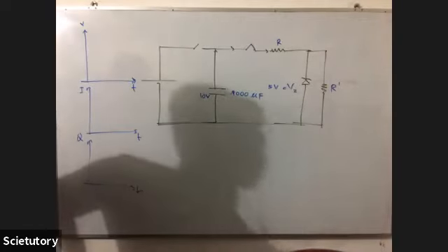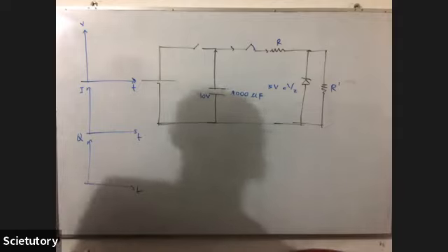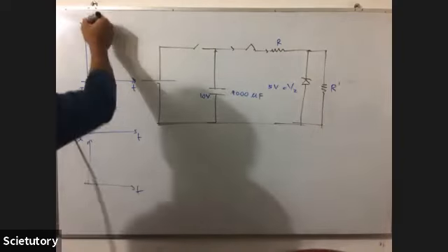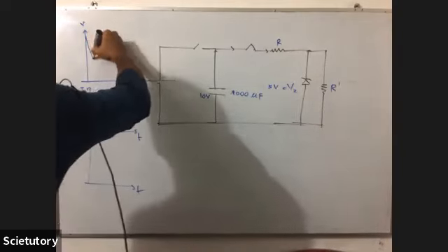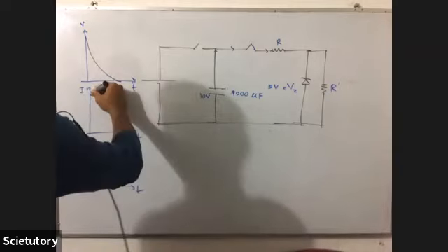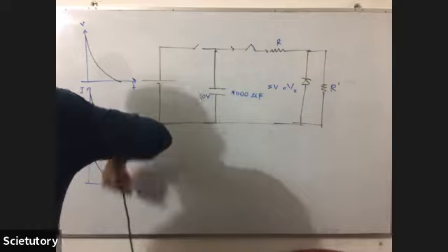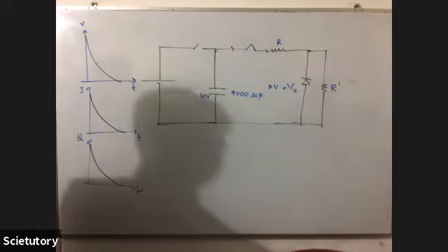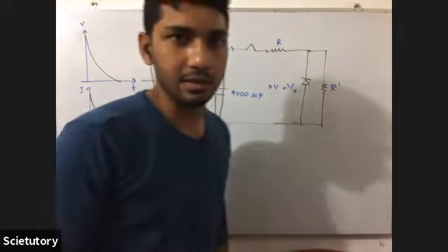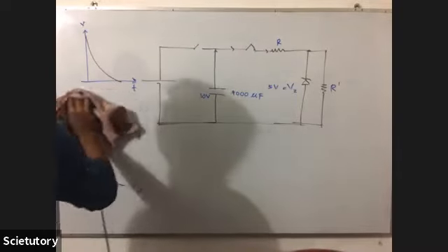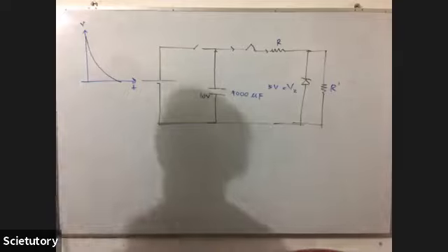When it's discharged, it rapidly supplies the charge to the rest of the circuit. So the voltage difference between the plates reduces and finally becomes zero. I is also reducing and becomes zero. Q is also reducing and becomes zero. The gradient should continuously decrease. So now let's only take this graph. Others are not much relevant for us.